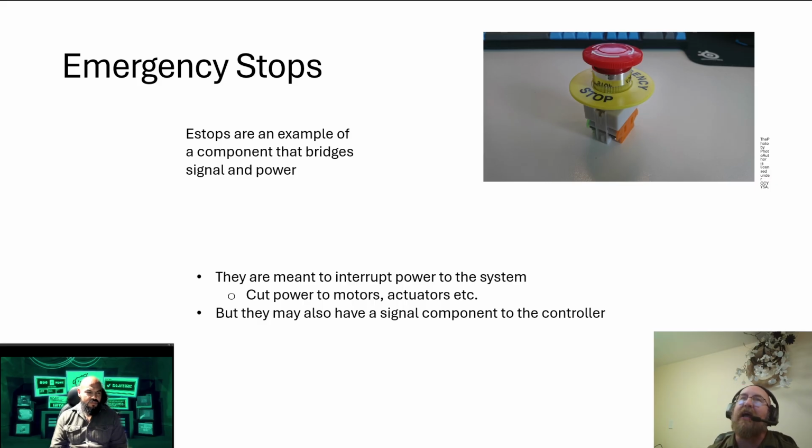This is how we're going to treat the e-stop on our systems. We're going to have the e-stop as an input into our VFD, because VFDs have one specific pin for the e-stop, and that makes the VFD cut power to the motor. So we're going to have a physical disconnect going to that e-stop pin on the VFD.